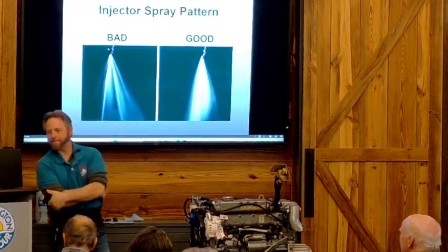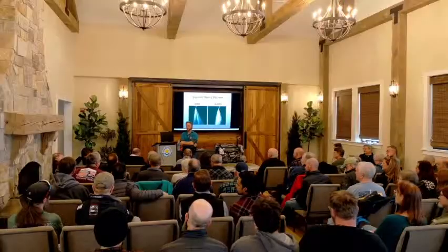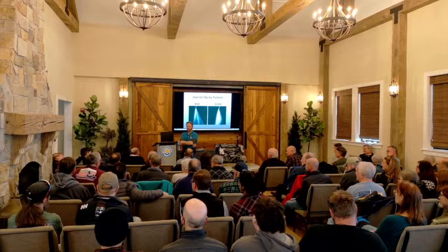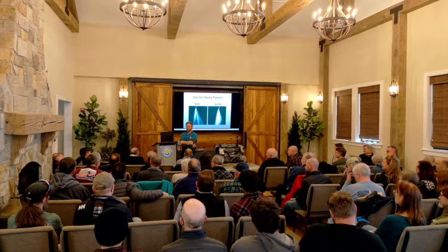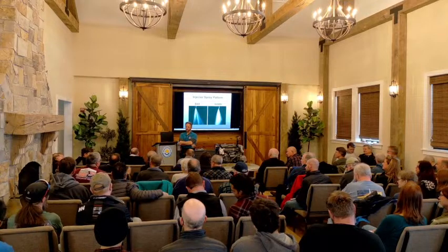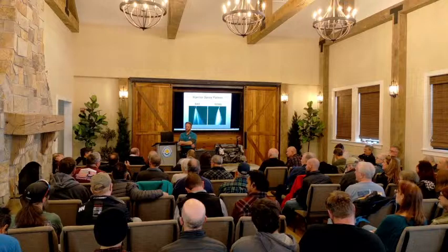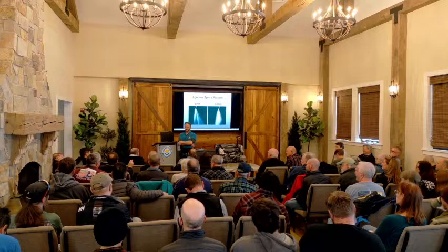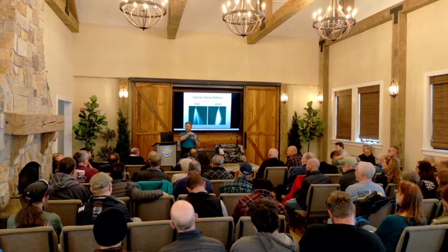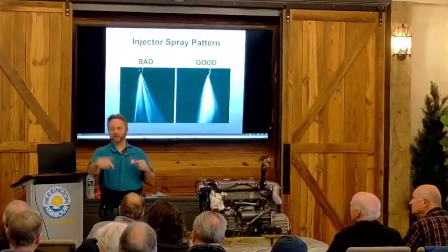You talked about oil changes, about being able to get, you never get 100% of the oil out, but 95 or whatever it is. Some of the MRs, the 3Js and the 4Js, you've got the dipstick where a lot of people are stuck out of it, but then there's also a plug that's not a drain plug, it's kind of on the side of the crankcase. Yeah, that plug's there, so if you need another dipstick that's easier to access on the other side, that's a hole for the dipstick.